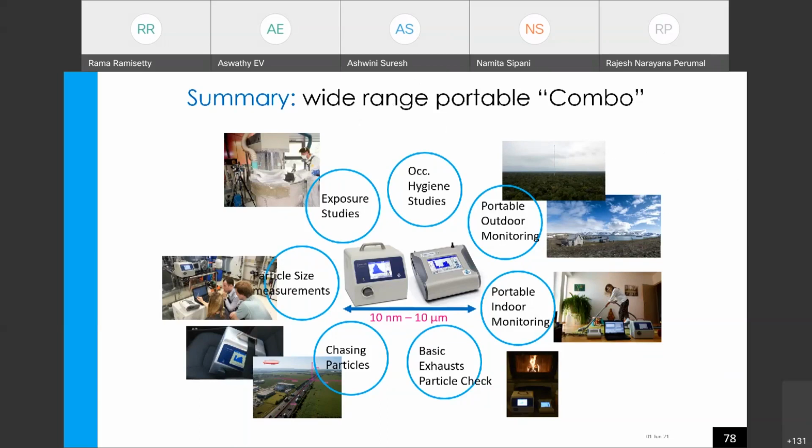If you want to measure particulate mass, then the range should be from 0.3 microns to at least up to 5 microns, so that you can measure the entire particle mass. Below that, if you want to measure very fine particle mass, then you have to go for different techniques. But since they contribute very little mass, people always look at the particle number instead of particle mass. For particle mass, it's always between 0.3 to 5 micron at least.